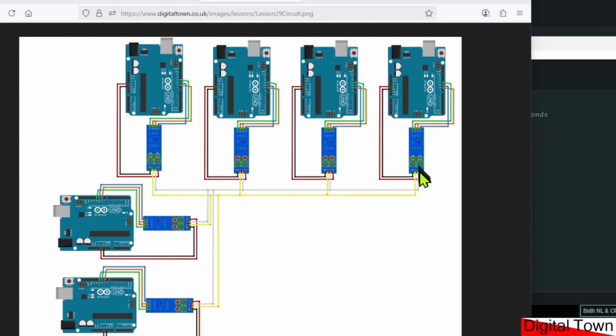And if you notice, when this then comes out of the RS485, I've got a white wire and a yellow wire. Now, this is what I would call an A wire and a B wire, as you'll see, and the communication, the signals that are sent through, are the difference in voltage between the two wires. Now that's a little bit of a weird one to get your head around. It's the difference in the voltage between the wires, which is not necessarily the difference between ground and the voltage going through the wires.